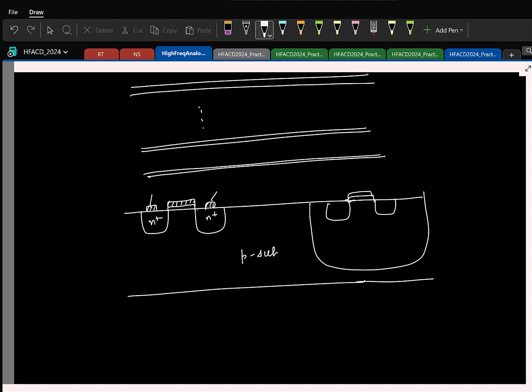And even the thickness you have for these metals, the spacing between the metals, and in general any spacing in this vertical dimension, they are not under your control. It is fixed by the fabrication process. So the only dimensions that you have control over are the other two sides. And that's why typically, although this is strictly a 3D thing, we draw the top view of this, looking from the top, because that gives you the two dimensions that are under your control.